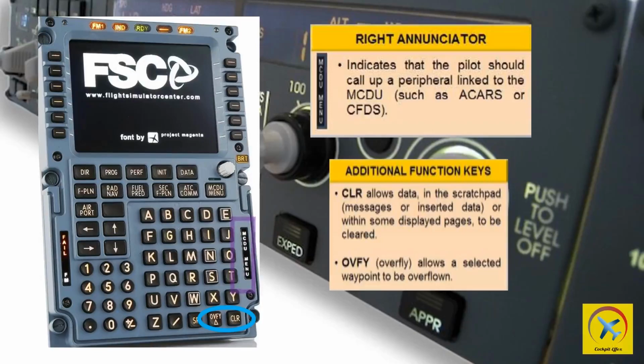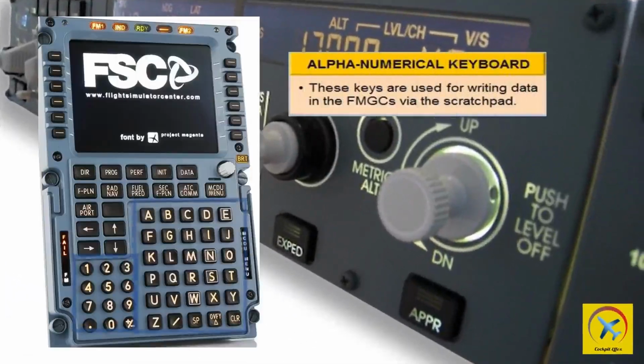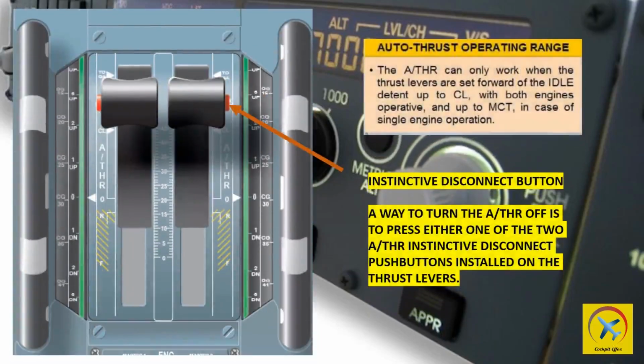The system can be changed using the MCDU menu key. The alphanumeric keys enable entry of letters and numbers into the scratch pad. The positive and negative key alternates between positive and negative figures. The slash key is used to separate pairs of entries in the same data field, for example wind direction slash speed, 270/110. The trailing entry of a pair must be preceded by a slash if it is entered alone, except for frequencies and identifiers entered on the radio navigation page.